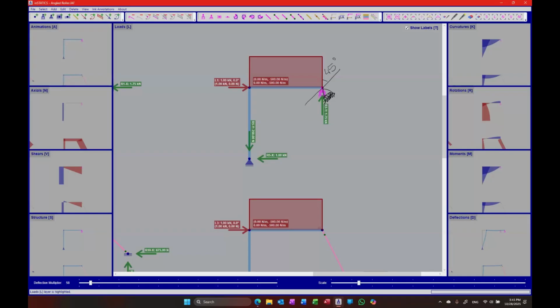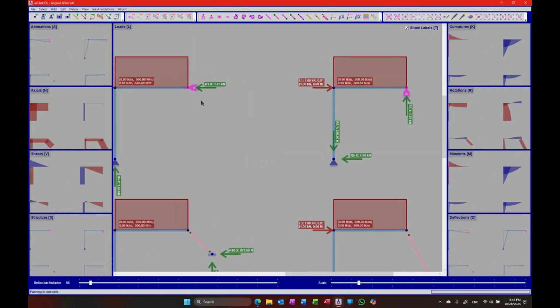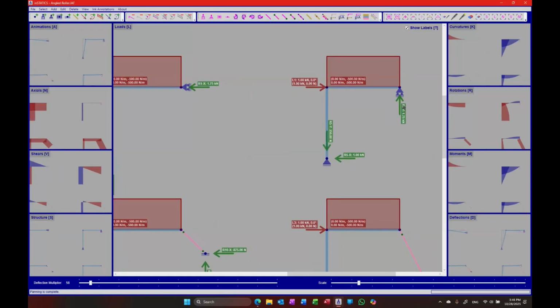because what do we normally do, guys? We find the degree of freedom that's going to be restricted by the support, and then in this case in the vertical direction, right, in this direction, and then we put a 1 there and then put a 0 at the displacement side, and that equation becomes just that. We say, okay, no deformations at this point. So when we solve the structure, we actually get 0 deformations in the vertical direction here, or 0 deformations in the horizontal direction here. But we don't have a coordinate for 45-degree angles.